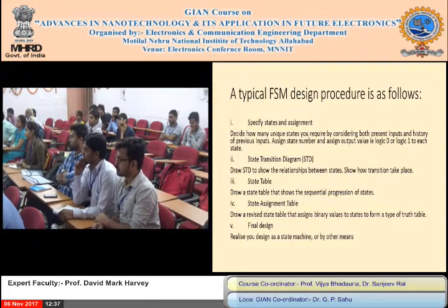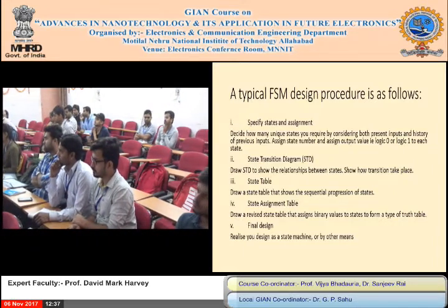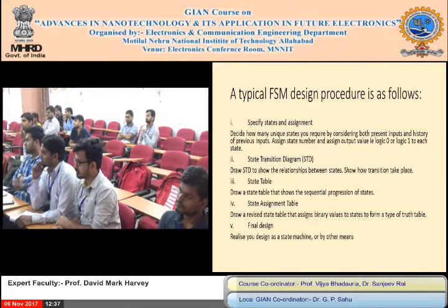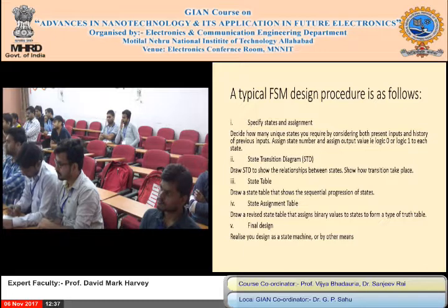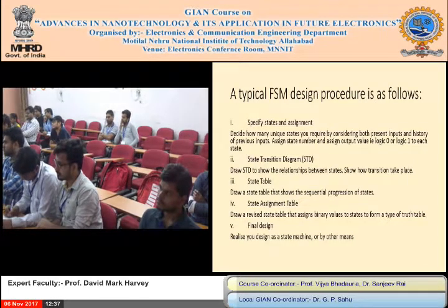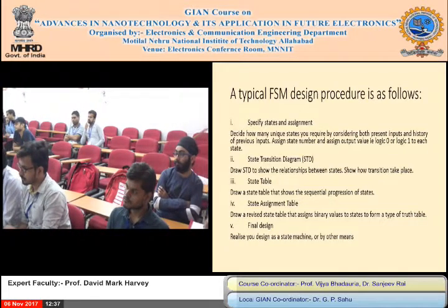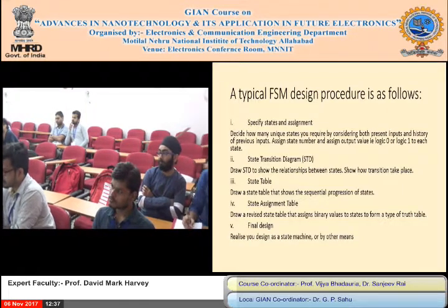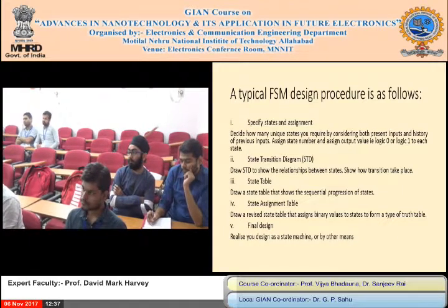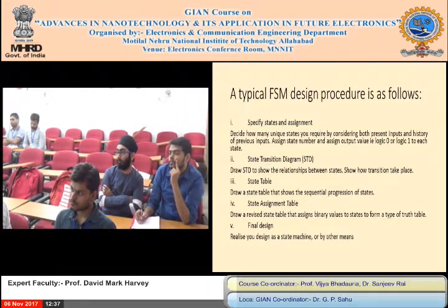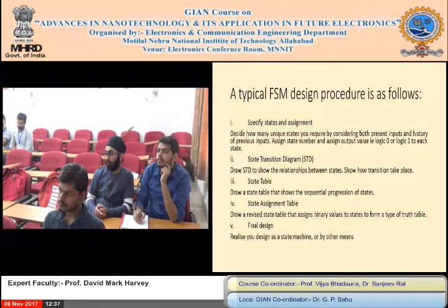Okay, so just to put this in a nutshell, every digital circuit can only have a number of states. 10 states, 20 states, 1,000 states. So it's limited. And as a designer, you try and fix it. So what you do as a designer, you have to specify the states to start with. Or if you're in a company, your boss might come down and say, I want you to design something to do this. And you may have a logic diagram or a truth table. So then you design from scratch. So you design the states, and in the design procedure, we give a state number. Each state should be unique when we start out. We draw this state transition diagram, STD.